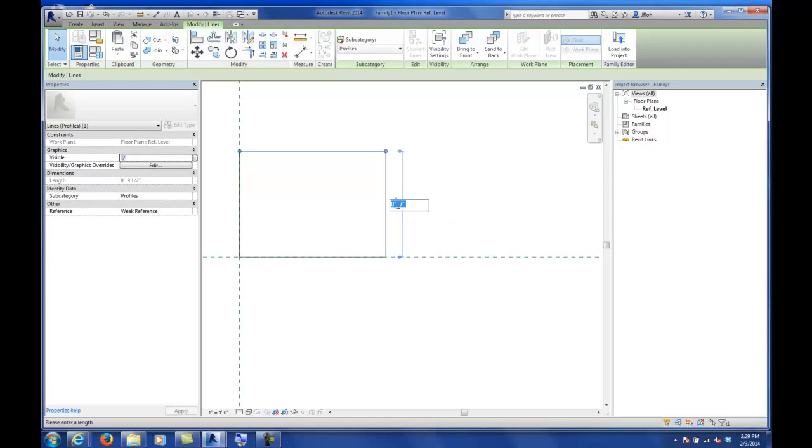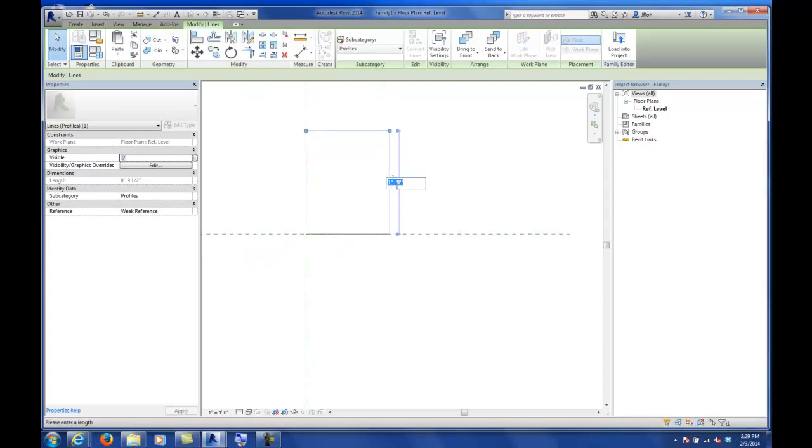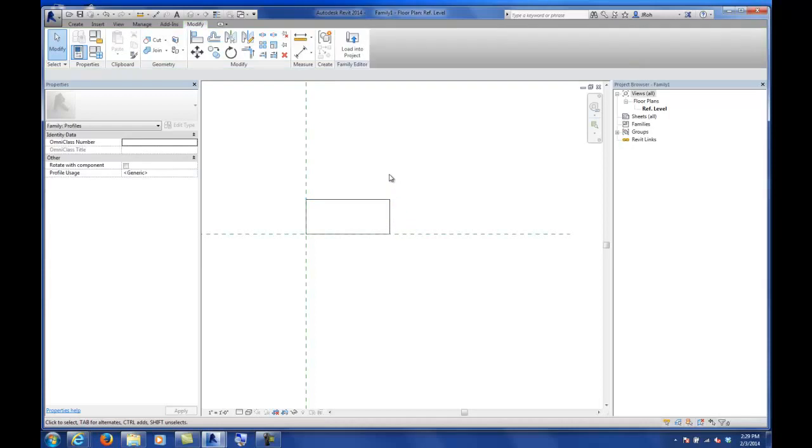It's a place where you can click on whatever your value might be. So I could left click on that. Mine happens to say 7 inches, and I could change that to 1 foot, or I could change it back to 4 inches and so on. That's the way in Revit we generally work. We're just going to be placing things, and then eventually you move things either by move commands or by these